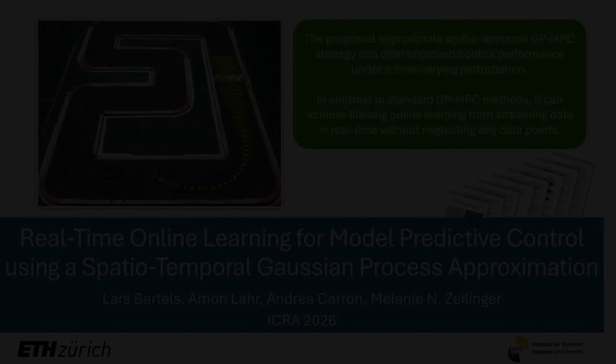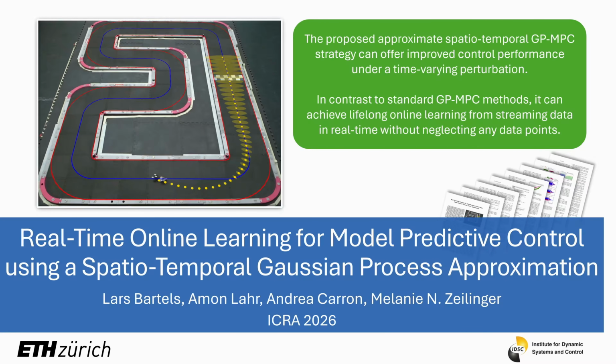Our experimental results showed that the proposed approximate spatio-temporal GP-MPC strategy can offer improved control performance under a time-varying perturbation. In contrast to standard GP-MPC methods, it can achieve lifelong online learning from streaming data in real time without discarding any data points.